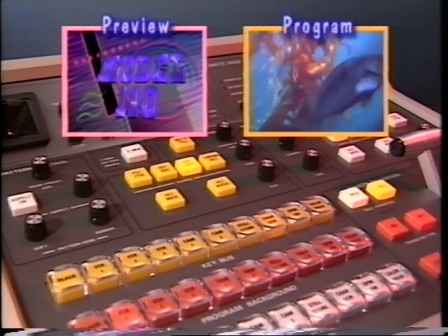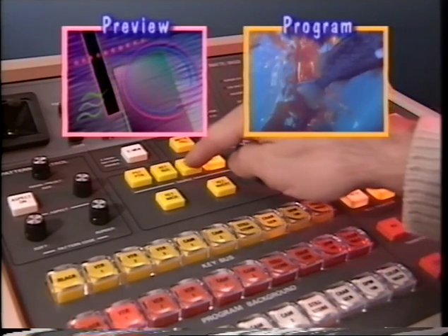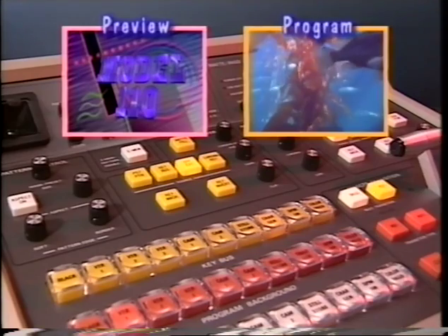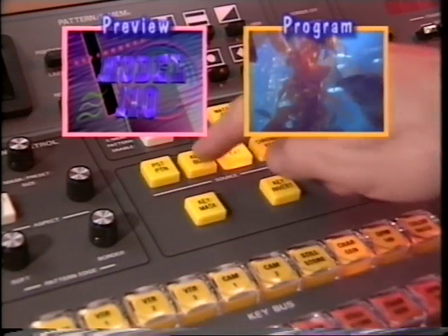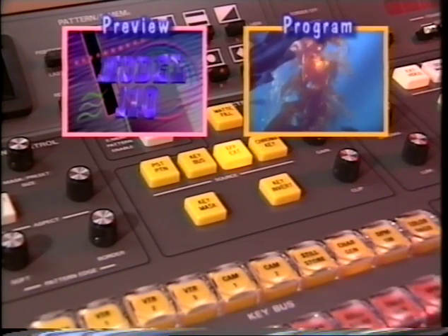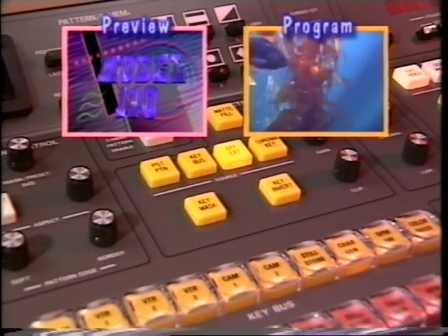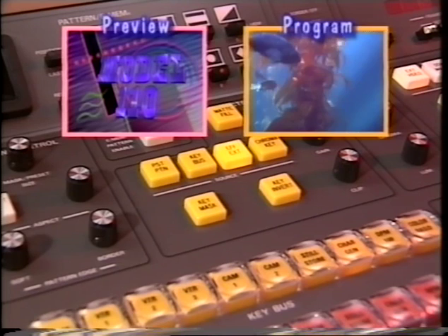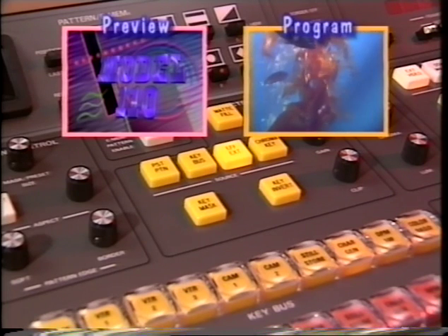The key source cuts a hole in the background scene. 2 possible luminance key sources can be selected on the effects keyer: either the output of the key bus or a separate external signal. An external key can be any signal you connect to the external key input, such as a graphics camera, character generator, or key source videotape.